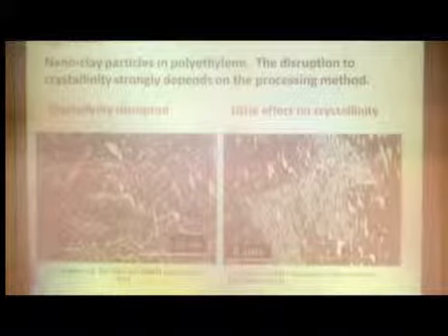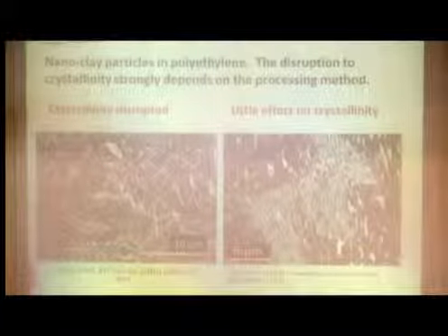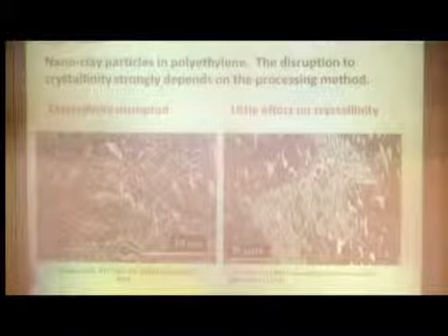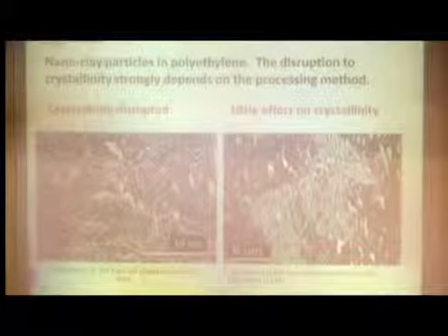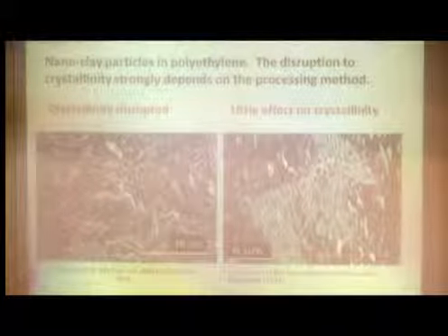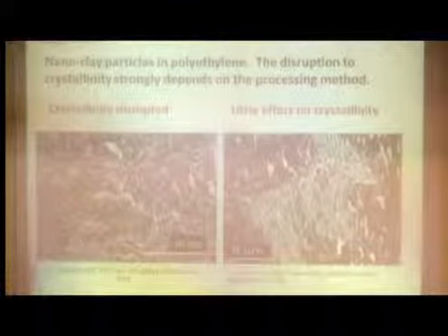polyethylene is trying to grow its crystals from these platelets, and then it immediately finds another platelet. And so you get loads and loads of little bits of crystals which are not very well defined. So you'll have to read the papers if you want to understand more about that. But what I'm trying to say is that it very much depends on how you actually process the material.